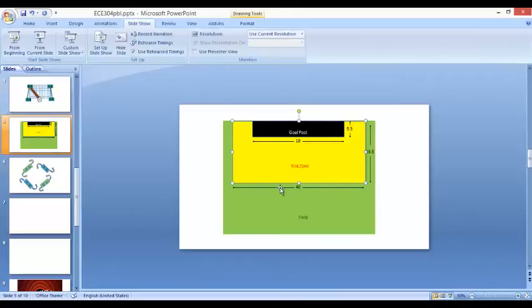The risk zone that we have found as 40 cm in length and 16.5 cm in breadth is the area in which if the ball is found then the goal will be scored. So when the 4 sensors detect the ball, we can find the length of the ball from each sensor and the angle that it makes with that point. Using these two parameters, we can find the perpendicular distance of the ball with respect to the goal. If this perpendicular distance is less than 5 or say 4 centimeter that we set as a threshold, then the servo motor that has been put to our goalie will move the goalie in that particular direction.